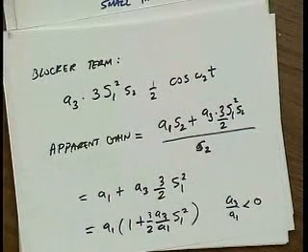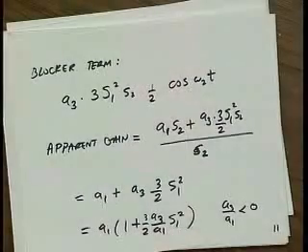Yes? So when we put an SNR, we do the signal in-band to the noise in-band, right? But basically, any out-of-band signal will be IM3 interference into in-band. So when we calculate noise, we have to integrate over the whole spectrum.